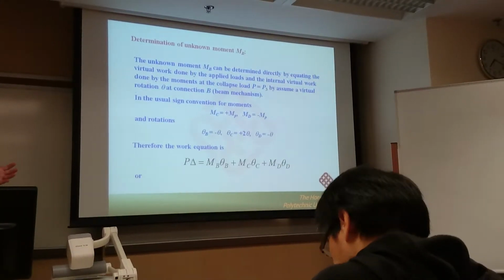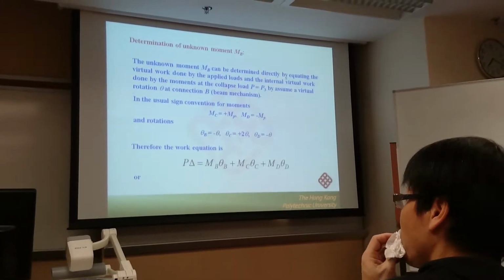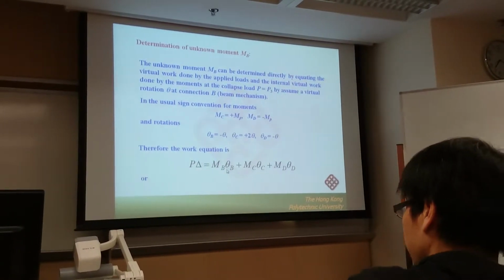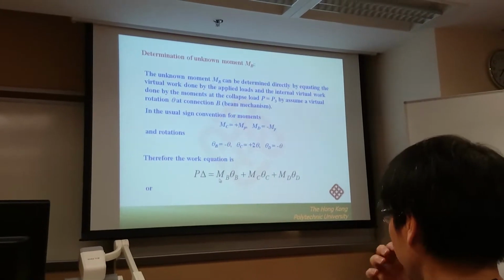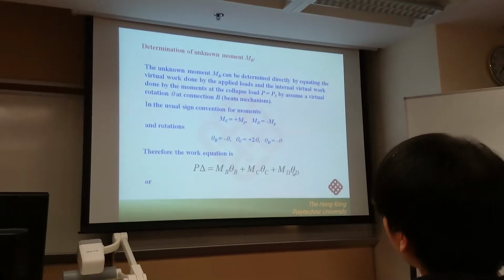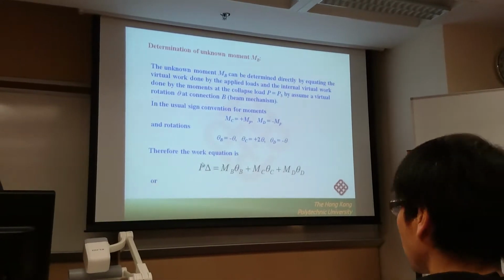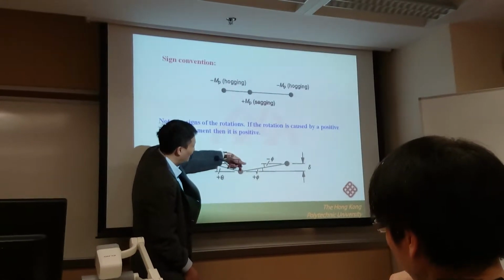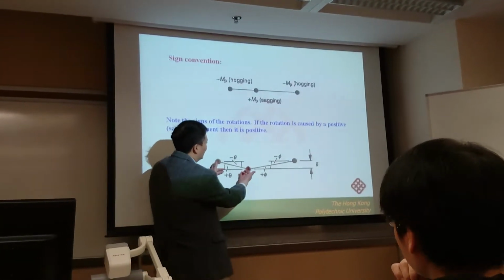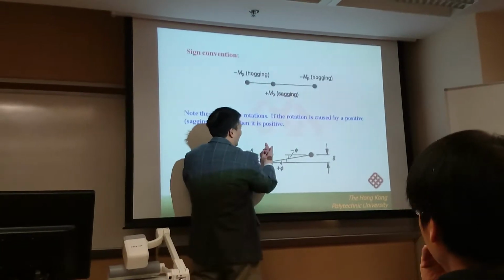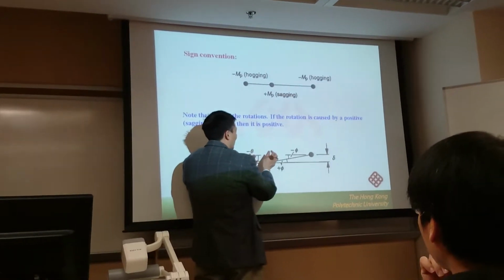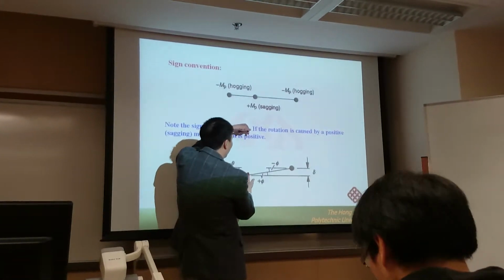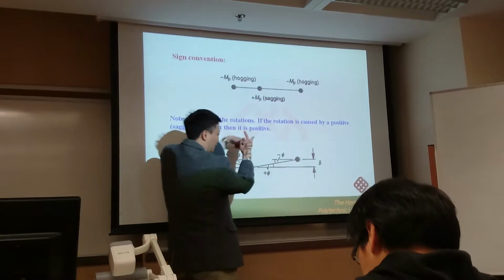Why? Actually, it is impossible to have a different solution. The solution is the same because not just the terms on the right side change, this term should also be changed because the force is applied in the downward direction. So if you assume the displacement is in the upward direction, the work done by the force is equal to negative P times delta. Because the displacement is in this direction and the force is in the opposite direction.